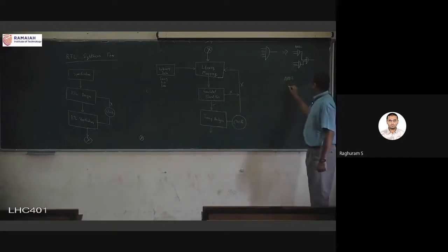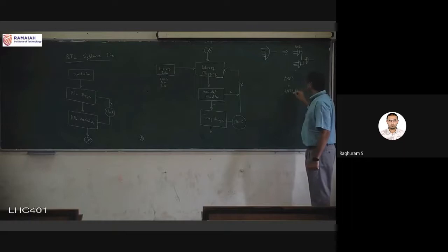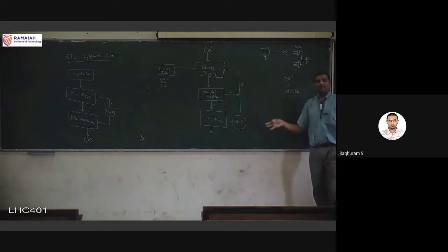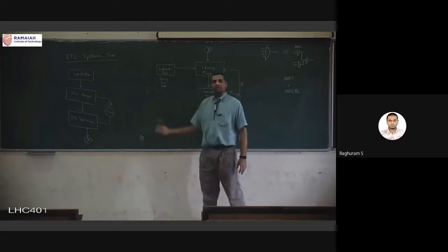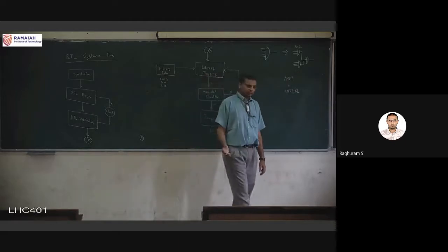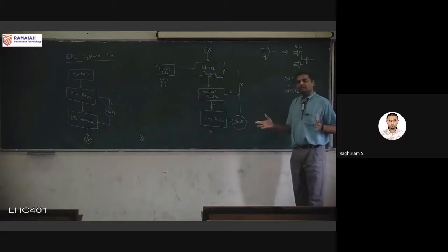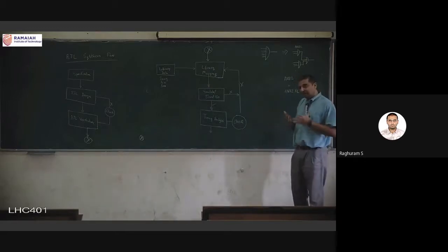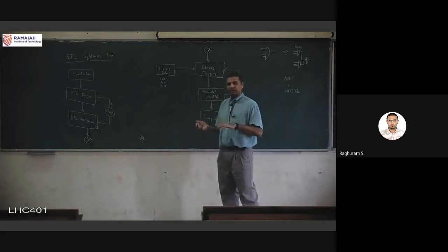So I might go from AND to AND XL, extra large, and as we will see in the third or fourth unit when we are talking more about time, if we make the size of the gate bigger, it becomes faster. Why? We will see more detail in the third or fourth unit.